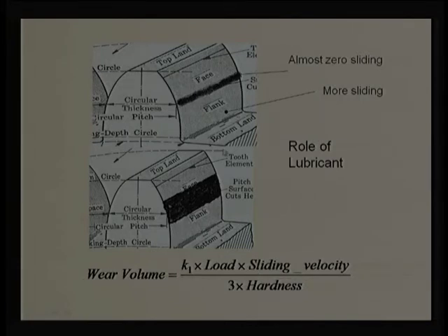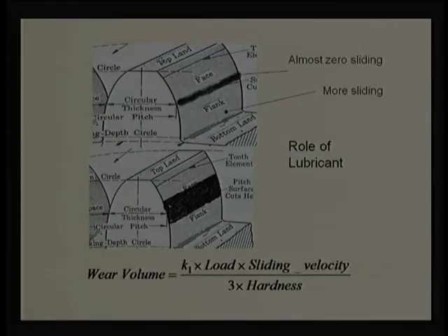So, many times we compare this as stub teeth, standard teeth and high contact ratio gears. We say that when this profile extends beyond a certain limit, it is going to give a high contact ratio, but along with the high contact ratio it is going to give very high sliding. High contact ratio is required from a force point of view. The higher the ratio, the lesser will be the force. Obviously, the stresses will be lesser, but with a high contact ratio, there will be more sliding, more friction.